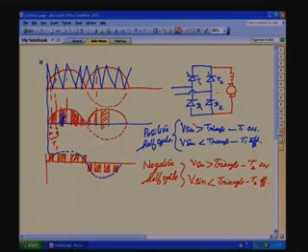As the sine amplitude decreases, let us take a case like this. The pulse duration, T1 will be on for very small durations in one period here. So, similarly the output DC will also vary. The triangle frequency is fixed, and the sine amplitude we will increase and decrease such that the output voltage is controlled. At the same time, the output ripple frequency is shifted to the high frequency PWM side.